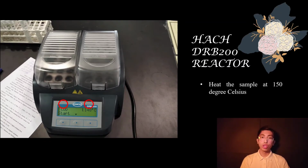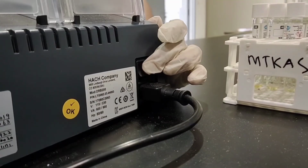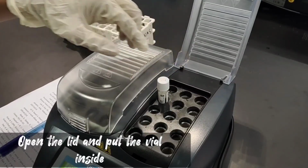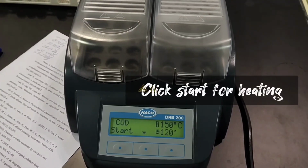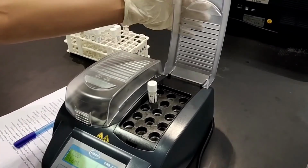The next video will show you how to use the DRB200 reactor. First, switch on the DRB200 reactor. Click the Start button for preheat. When the temperature is 150 Celsius, open the protected lid and put the vials in it. Close the protected lid and click the Start button to start heating. When the vials have been heated for 2 hours, open the protected lid and take out the vials.